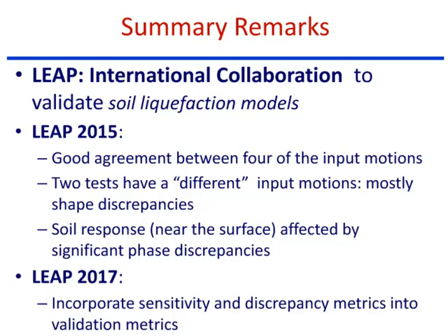Yeah, the answer is that the vertical effective stress equal to 0 was used as a measure of total liquefaction, and the pore water pressure was measured for all the tests. So we had a central array as well as left and right arrays, and they included pore pressure measurements.